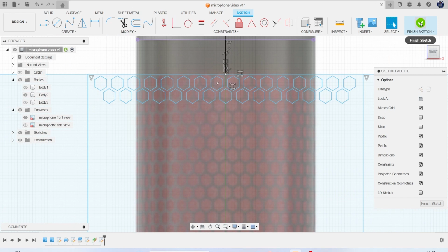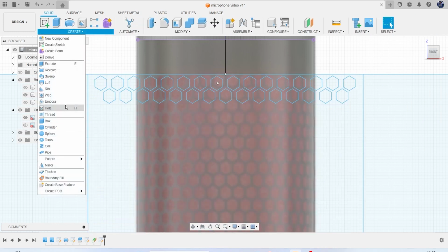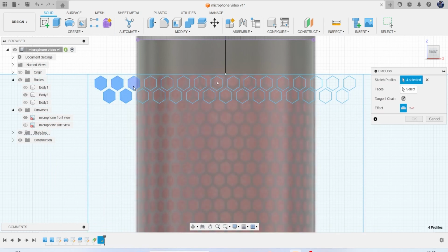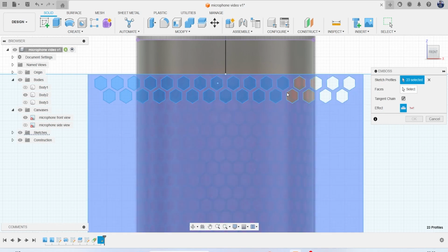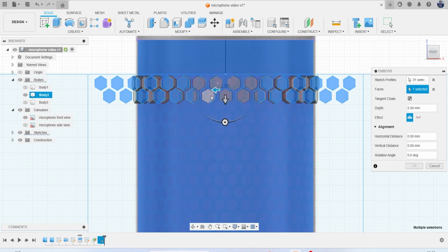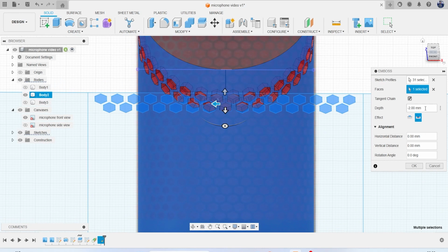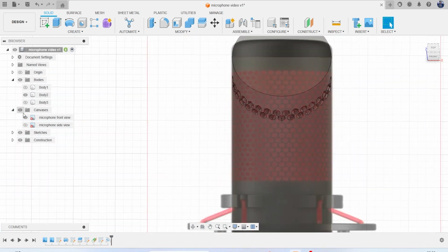And then what we want to do is, let's finish sketch, create, let's do emboss, let's grab one of these profiles. Let's grab this face, we're going to go in, let's do maybe more, let's do like -4, a bit too much, let's do -3, and enter. So you can see if I turn the canvas off,